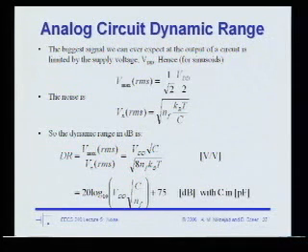And because we're using active circuits, there's an extra factor in there, right? And we're calling that NF. Don't confuse that with the noise figure, by the way. It's just a notation that tells you the additional noise that's being added by the amplifier. And last lecture we did a simple calculation of NF. So dynamic range is just the maximum signal over the minimum signal. That's the signal range over which your analog circuit can process, right?